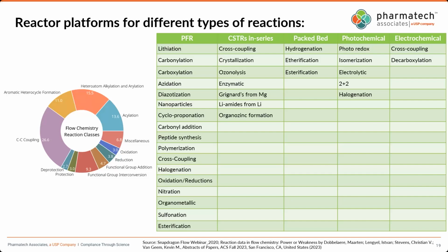So here, this is a very nice table that I always use whenever I have a question of what type of reactor I should use. The table on the right-hand side tells you certain types of chemical transformations and what reactor is suited. For example, for the CSTRs, the Grignard reactions, although they are exothermic, are preferred in CSTRs because that involves feeding of magnesium and formation of slurries.